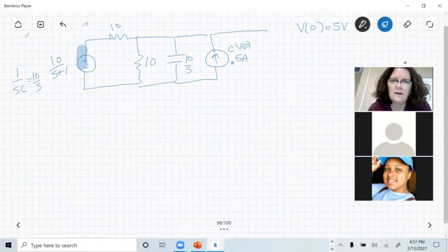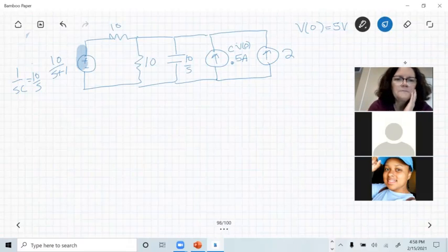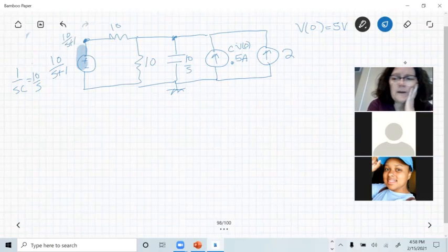My delta of t function over there, I take the Laplace transform of it. The Laplace transform of delta of t is just 1. Since that was 2 delta of t, that becomes 2. I'm still going to write the node voltage equations. This will be the last problem I do today. I don't have to write one here, because if I pick my ground node down here, I know the voltage at this point. It's 10 over S plus 1. So don't write an extra equation. This is going to be my VA.